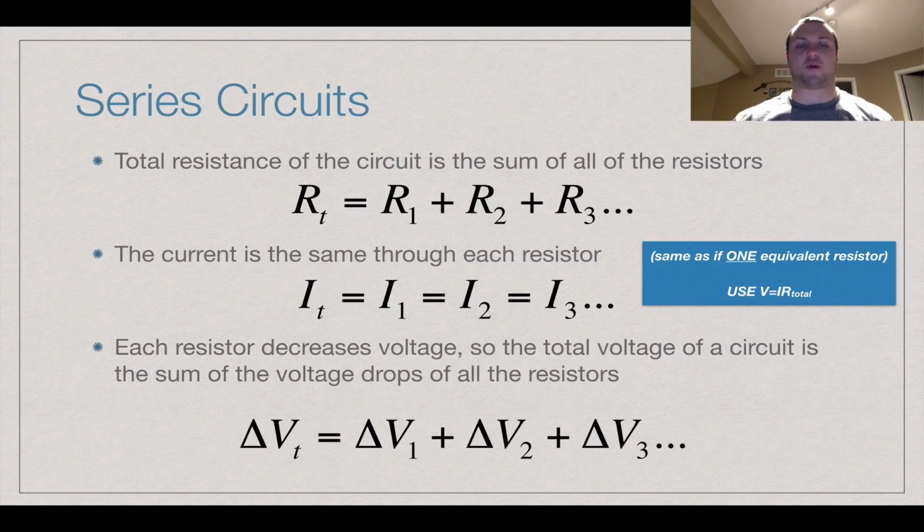And we're going to look at that and go, okay, how much voltage did this resistor use based on the total current? How much voltage did this resistor use based on the total current? And that's going to allow us to find that overall voltage of the entire circuit.